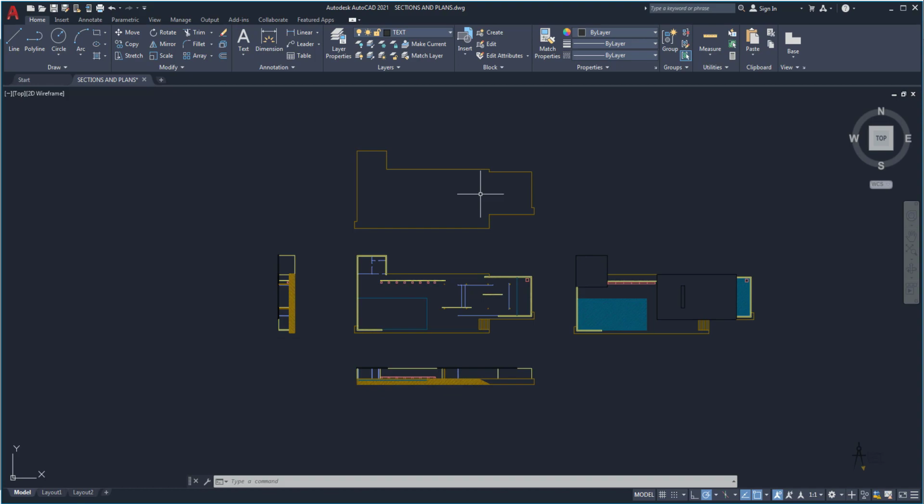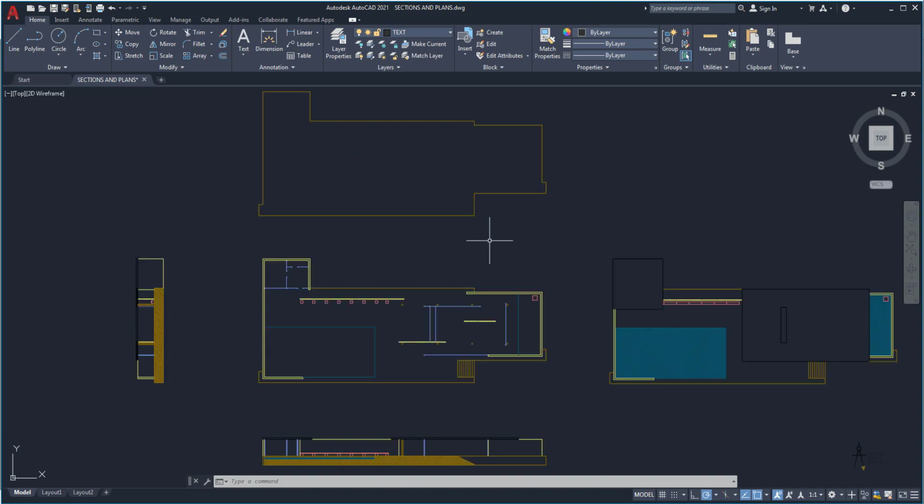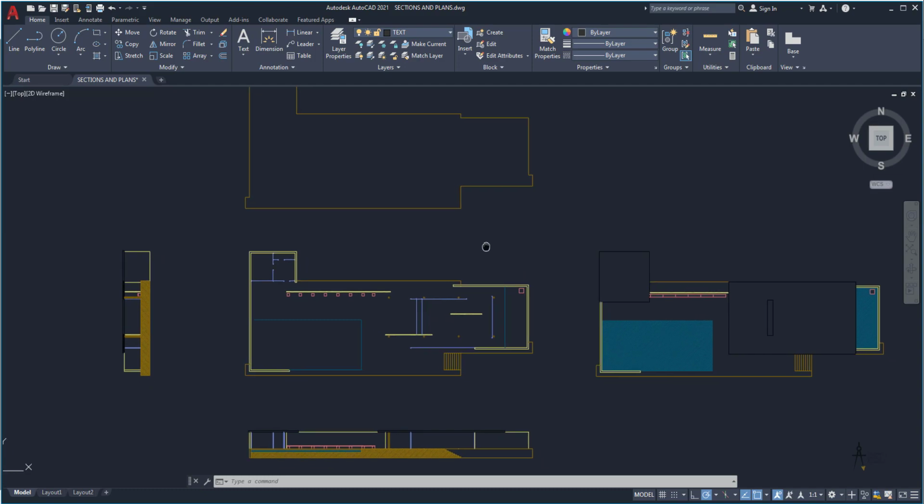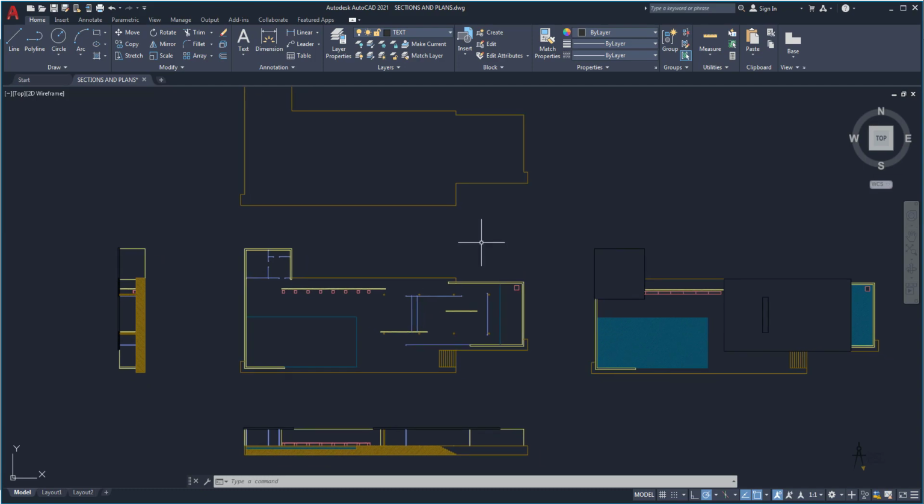You can, if you like, go line by line. If you really know your project very well, or the project doesn't have a lot of lines or hatchings or whatever, you can go line by line. For example, now I've got 2 hatchings, the pool, which I'm going to get rid of. But what is recommended is that you get the knack of isolating your layers.